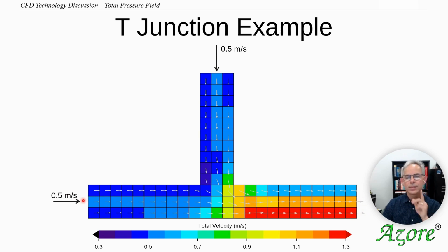One thing I've shown here is, CFD predictions often come in these filled contours where they look continuous, but here I've shown the CFD predictions on a cell-by-cell basis. All CFD predictions are basically a bunch of point data, and that's really what you need to mine.